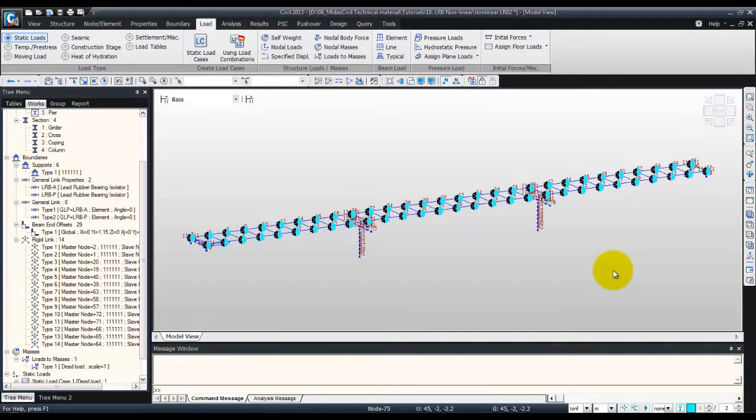And in order to reflect the dead load in the time history analysis, the time varying static load function is used. This function basically creates a condition in which the dead load is in place at the time of performing the time history analysis for the seismic load. So I will create a ramp function and assign it to the static dead load, and the El Centro data, which is used for the seismic load, will be created afterwards.